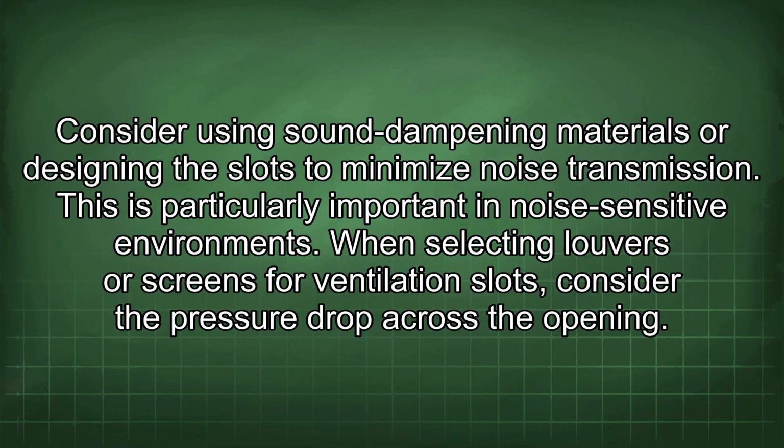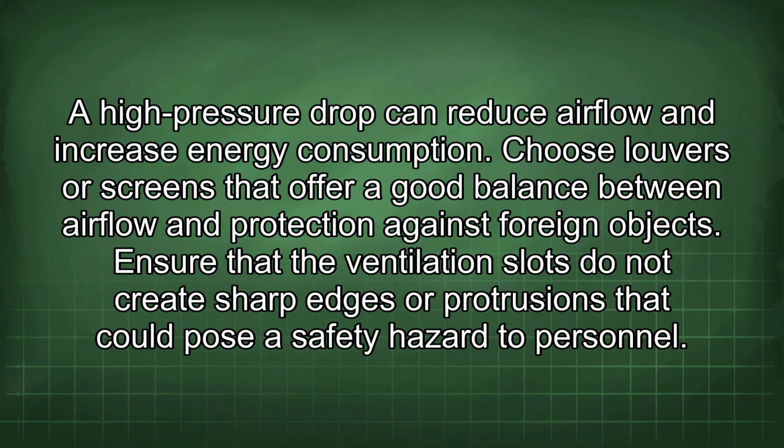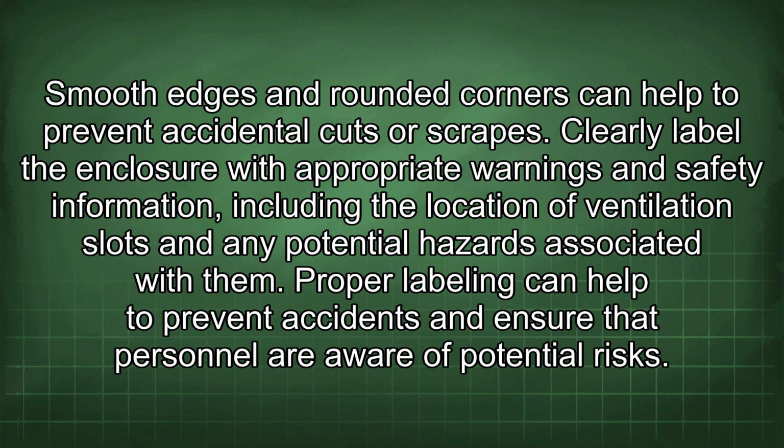When selecting louvers or screens for ventilation slots, consider the pressure drop across the opening. A high pressure drop can reduce airflow and increase energy consumption. Choose louvers or screens that offer a good balance between airflow and protection against foreign objects. Ensure that the ventilation slots do not create sharp edges or protrusions that could pose a safety hazard to personnel. Smooth edges and rounded corners can help to prevent accidental cuts or scrapes.